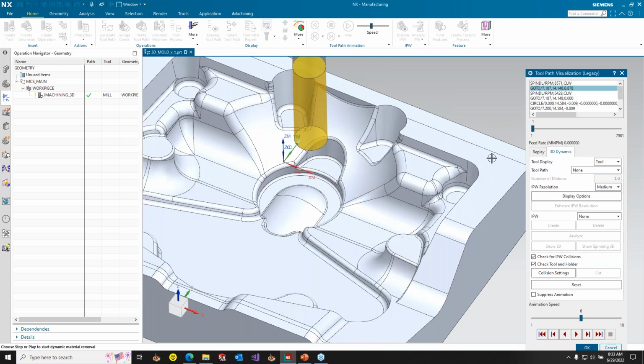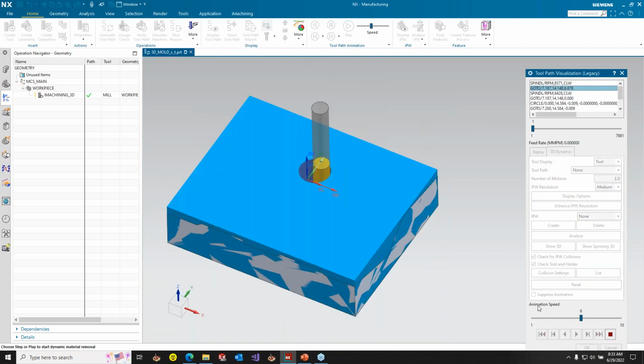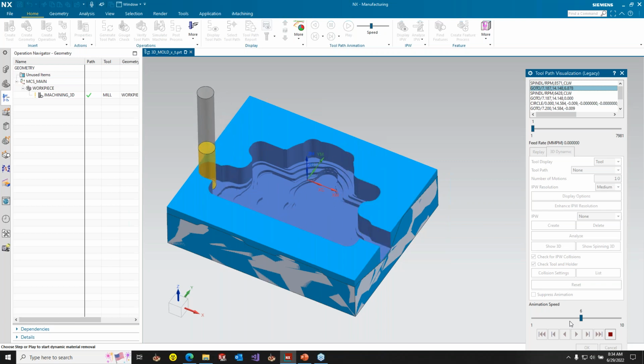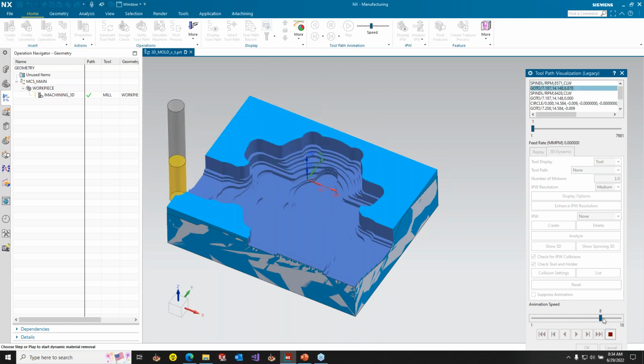So let's verify this toolpath. We will click simulate. As we know from iMachining, we always want to cut deep. So as we see here in this cavity, we found the deepest part of the model. It does that deep depth of cut, and now we work upward with the flute. That gives us our largest metal removal rate and the best ability in the cutting, because one of the main points of iMachining is being able to cut deep depths of cut and not shallow depths of cut, which is tougher on the tool. So here it's going to finish machining around the part.